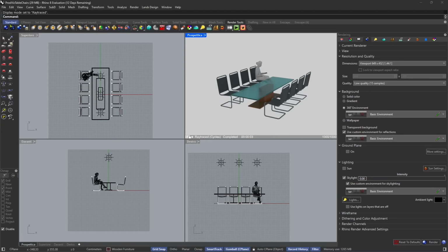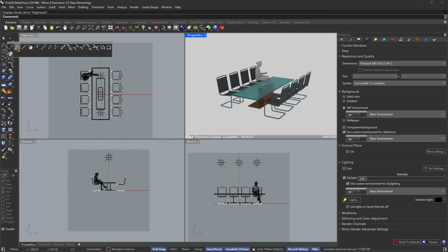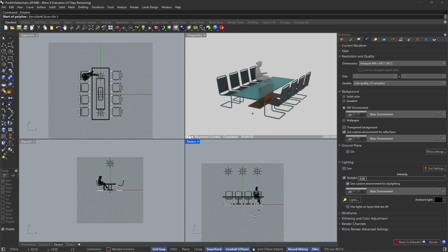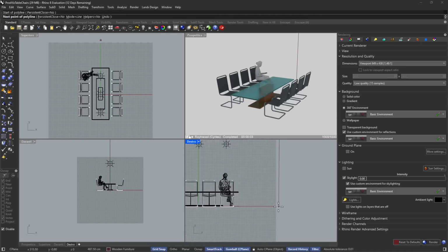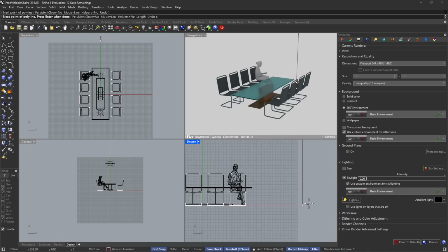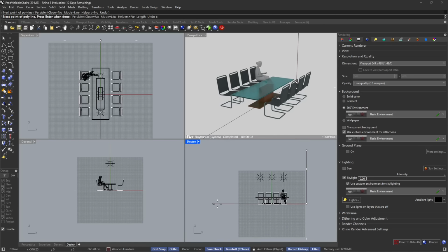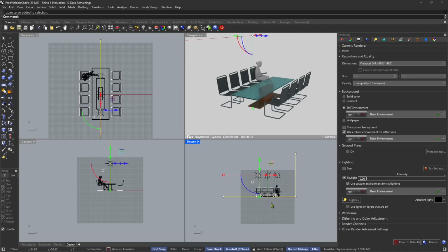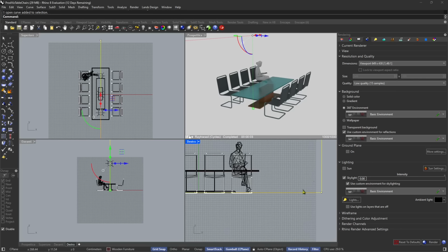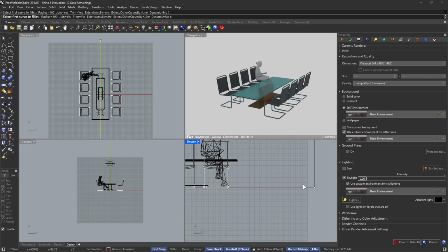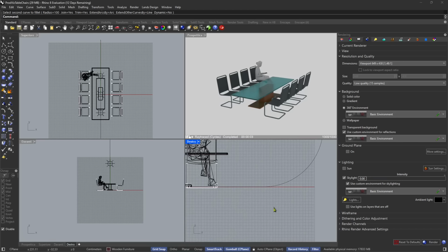So to construct the studio, I'm just going to go in the polyline and choose the correct view, which in my case is going to be this. And just going to draw like an L shape. I'm going to go all the way to the bottom here to the X axis, and then I'm going to go all the way here like this, and then right click. So I'm creating a backdrop that you see in the studios. So to do that, I'm going to add a fillet. I'm going to put 1 meter fillet or 100 centimeters. Click on one side, on the other, and there you go.